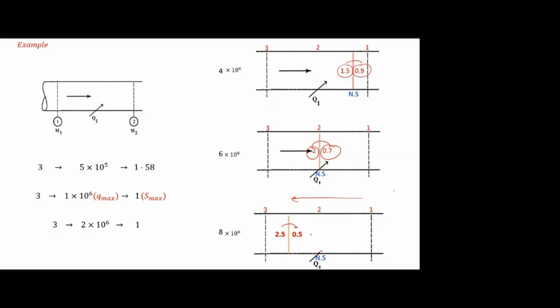Then with heat addition, the subsonic flow gets accelerated and reaches 1. So at the back side it is always 1. Only this normal shock forms inside and changes the flow condition inside. This side also Mach number 3 is fixed. Is it clear? Yes, sir. So this is how the flow adjusts for Q greater than Q max for subsonic and supersonic.